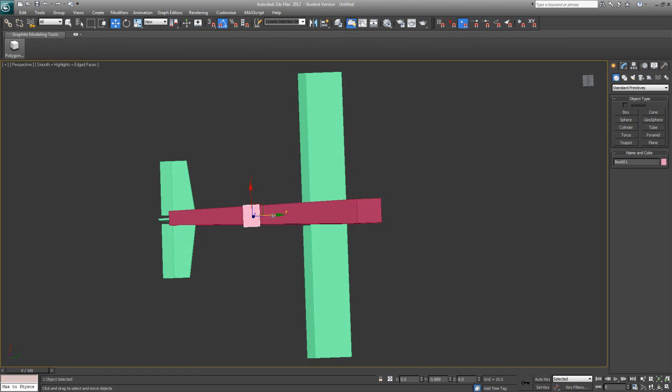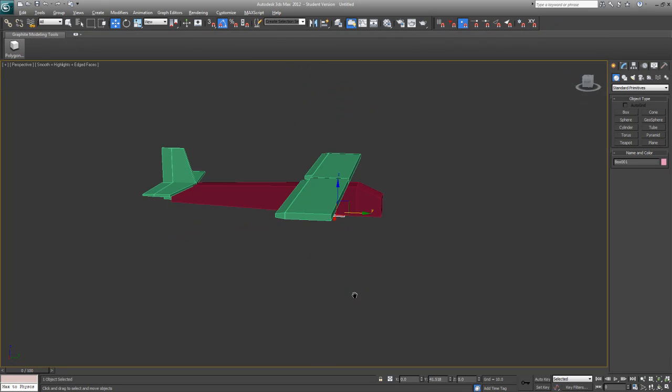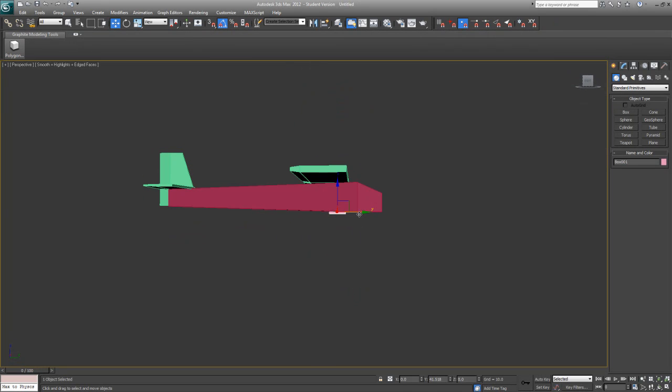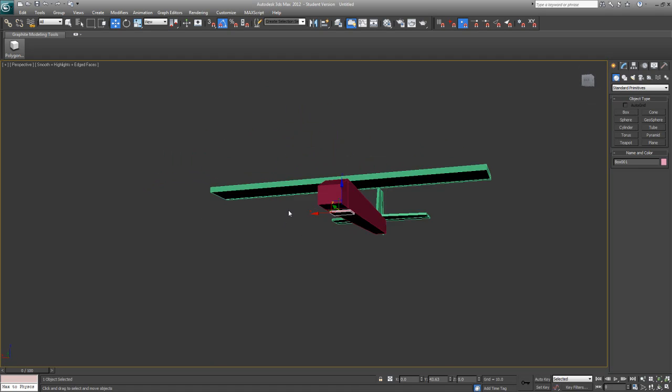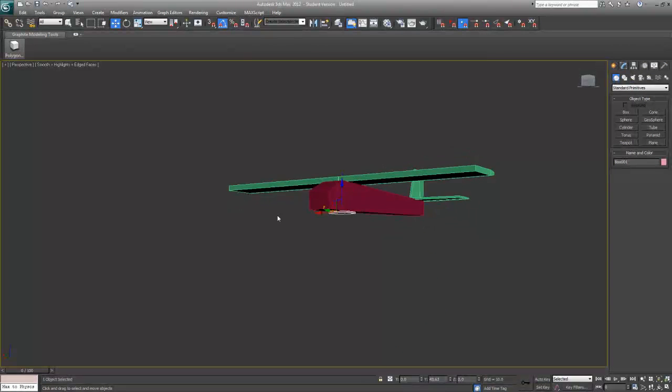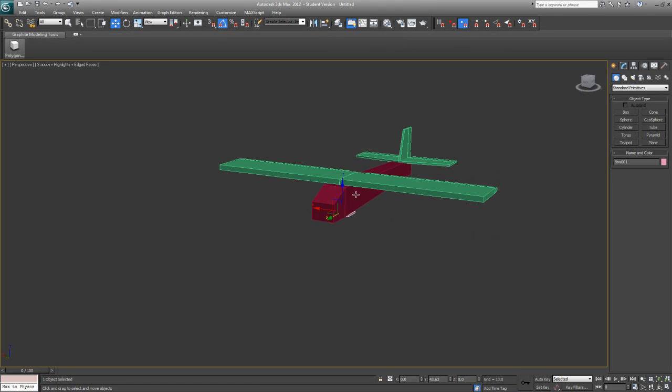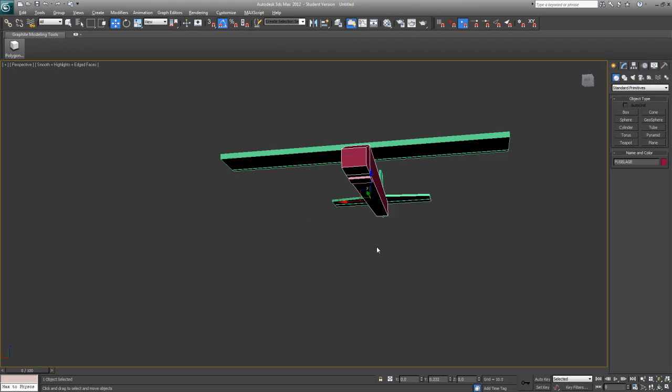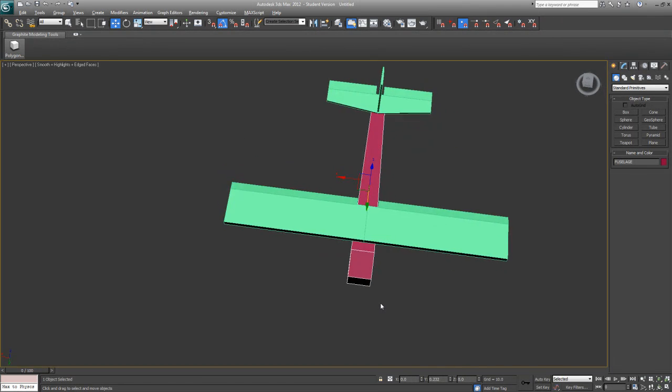Now I'm fairly centered on the fuselage because I've really never centered the fuselage or anything yet. So I want to bring this just in front of where the CG would be, and if you know anything about airplanes, we're looking at about a quarter to 33% back from the leading edge of the wing. So I want to be ahead of that, so I'm going to be kind of even with the leading edge, I think. Alright, this width is pretty good. That was a pretty good guess, I guess. Alright, let's center that fuse up while we're at it. That'll make things look a little nicer with the bottom part.